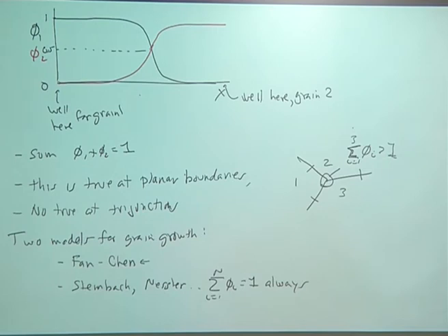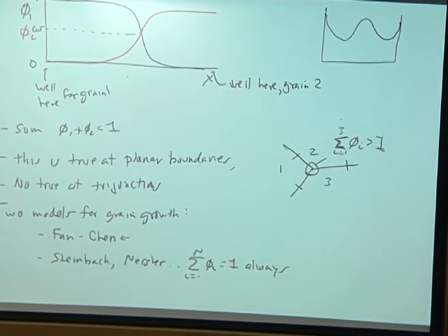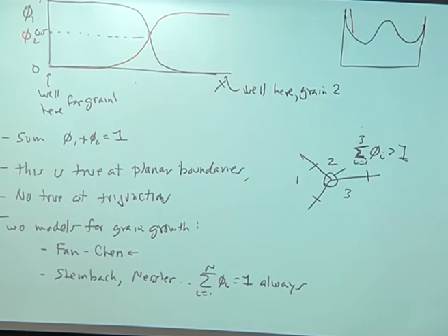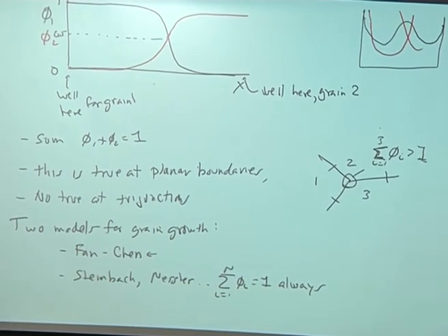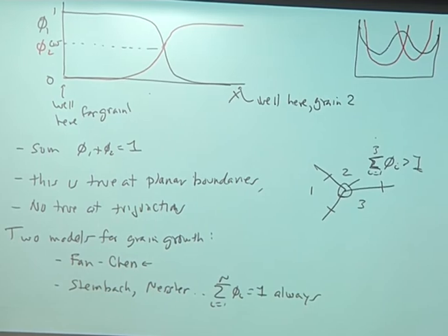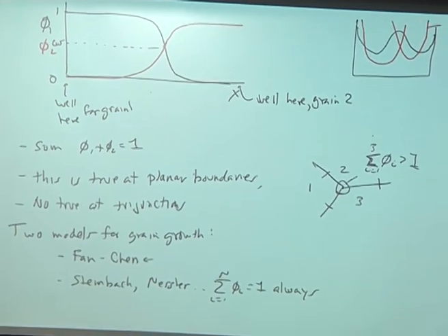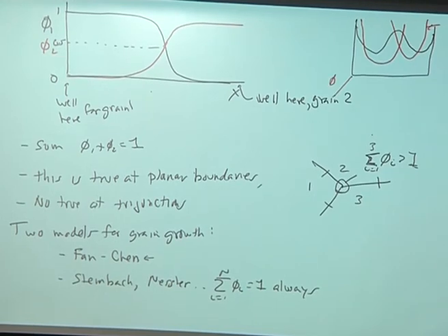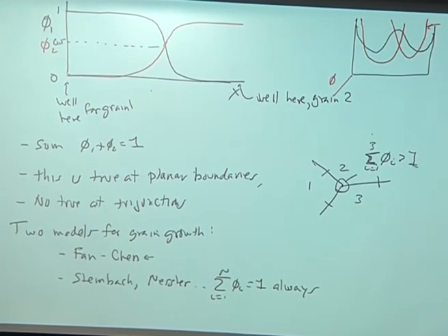Okay. The other thing I want to point out here is when we're talking about phase field free energies, and we had begun the discussion using the Cahn-Hilliard equation. That had a free energy function that looked like this, and I said that, well, in most cases, free energy functions are not continuous like that, but they look kind of like this. And how do you put these together? How do you deal with these problems? Well, you add an order parameter in that direction, and you use exactly this model.